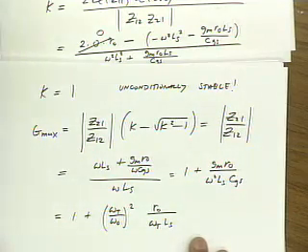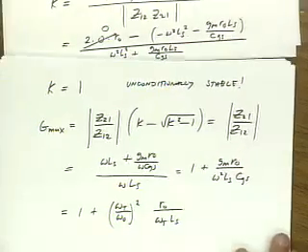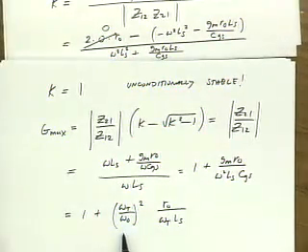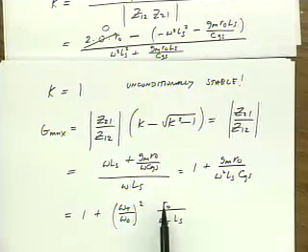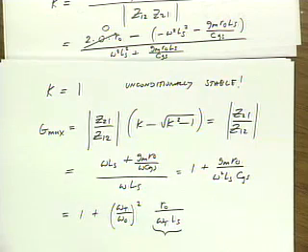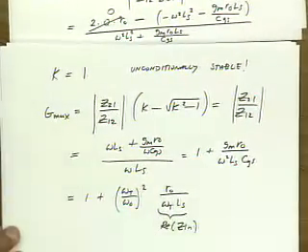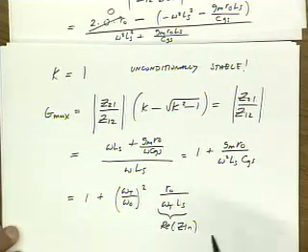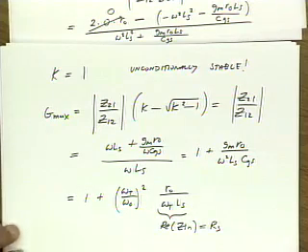It's basically a ratio of the omega T of the device and the operating frequency, and a ratio between Ro and a resistance equal to omega T Ls. Now remember omega T Ls, because what we're going to show is this is actually equal to the real part of Zin. And we know that we get maximum gain when we impedance match, and so this is actually going to equal Rs, the source resistance. Okay? Any questions about this calculation?